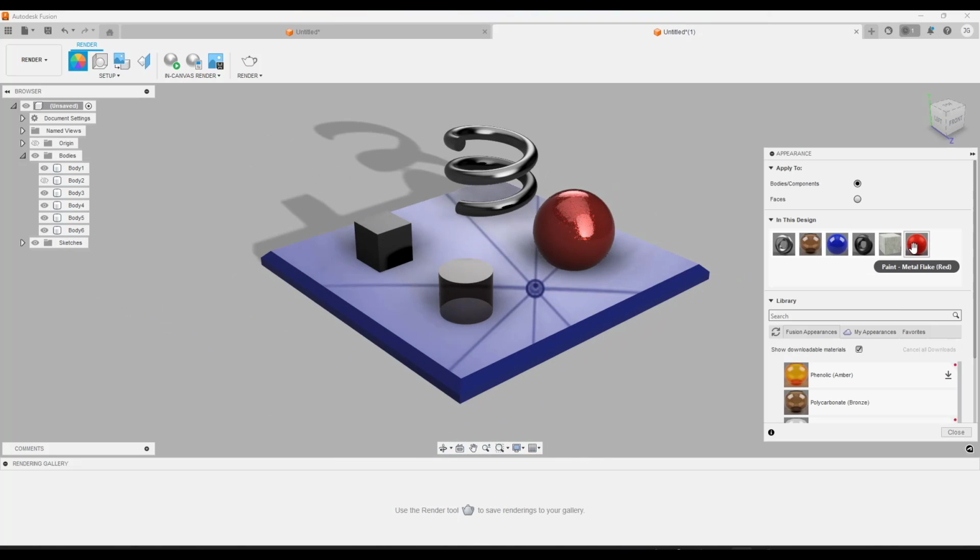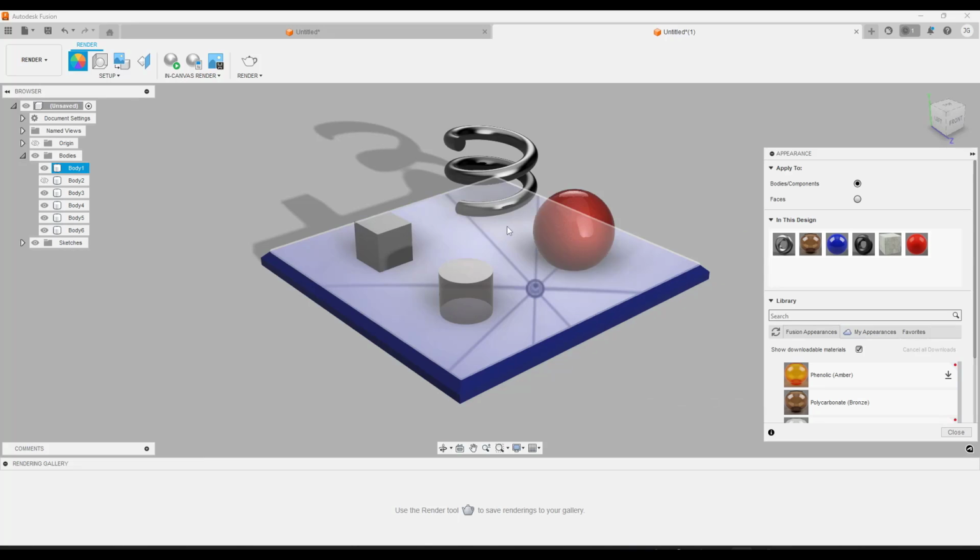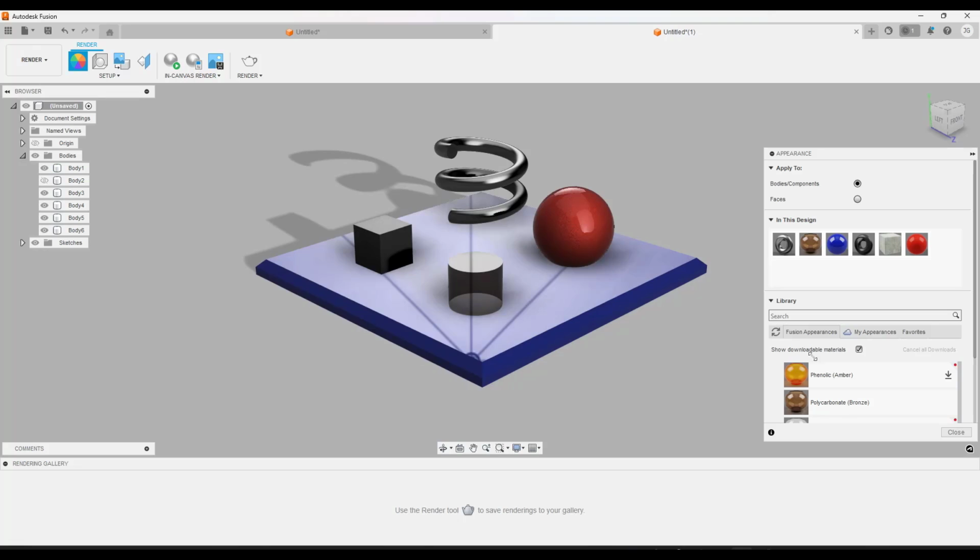And so what I really want you to understand is just the fundamentals of within different materials, roughness is going to set how much an object reflects inside your 3D space. So in this case, notice how this is setting the reflection of the objects. It's making it look more dull. Notice how if I bring the reflectance down, that's going to affect how much the light is reflecting off of the object. But you can adjust those things really quickly within the materials themselves.